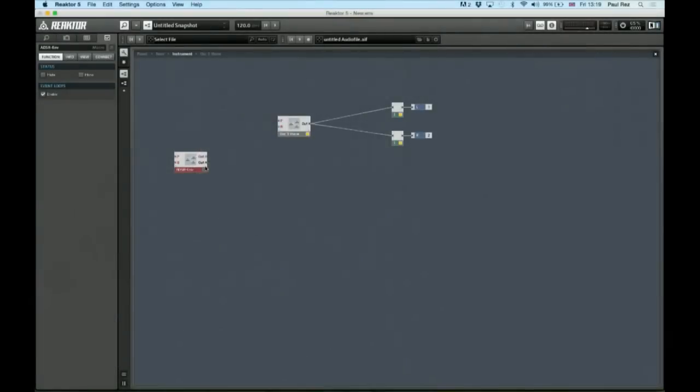And the red controllers are event controllers. They're basically kind of synonymous with CV controls that you used to get on old modular synthesizers. Yep, so low voltage, basically control messages. Mm-hmm. And you use it to send things like MIDI, pitch information, that kind of stuff. So we're going to take from the black output and connect it to our amplitude input. And you can see immediately the terminal turns black when you do that, so it knows it's receiving amp information.